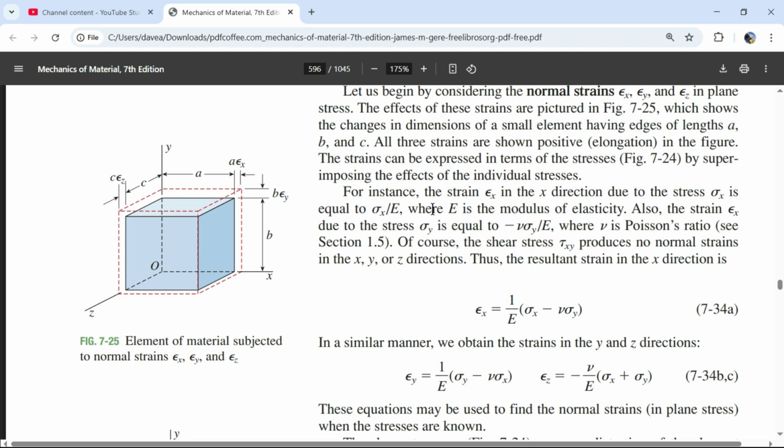So we can say when we have that stress in the y, we are generating a stress in the x direction that's negative, and it's equal to the number for the stress in the y times the ratio 0.3. So 30% of that 58,000 is actually wanting to pull it this way. Cool. Where this v is Poisson's ratio.